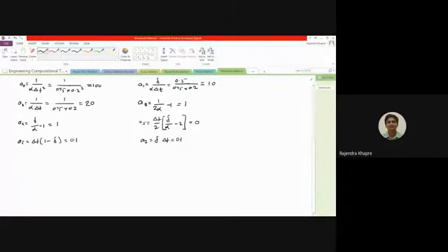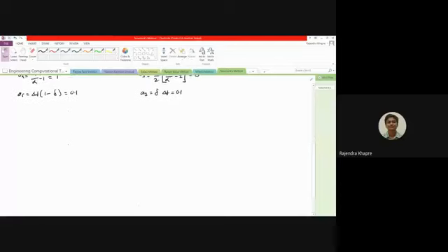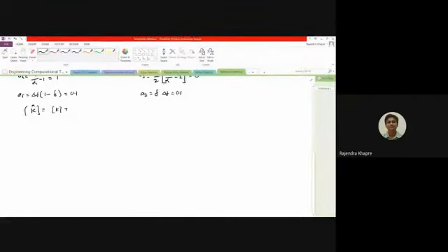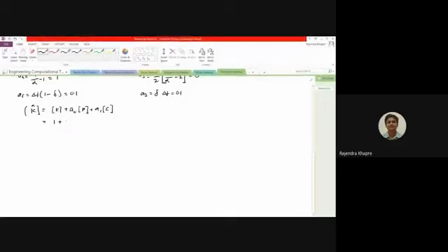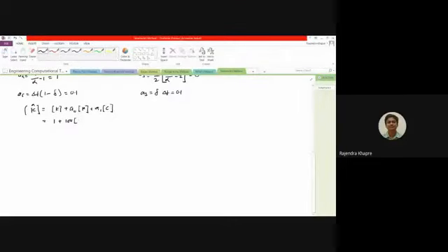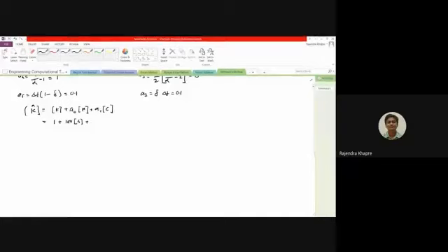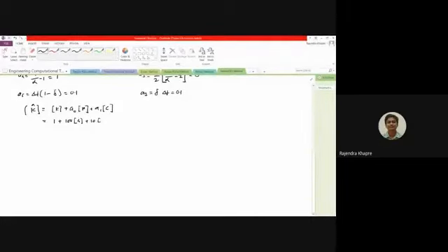matrix. So your effective stiffness matrix can be calculated as k equals, just now we have seen, k plus a0 times m, plus a1 times c. So if you substitute the values, your stiffness matrix comes out to be 1, a0 is coming out to be 100, and your mass matrix we have seen as 4, plus a1, the value of a1 just now we have calculated as 10, and the c value is 2.